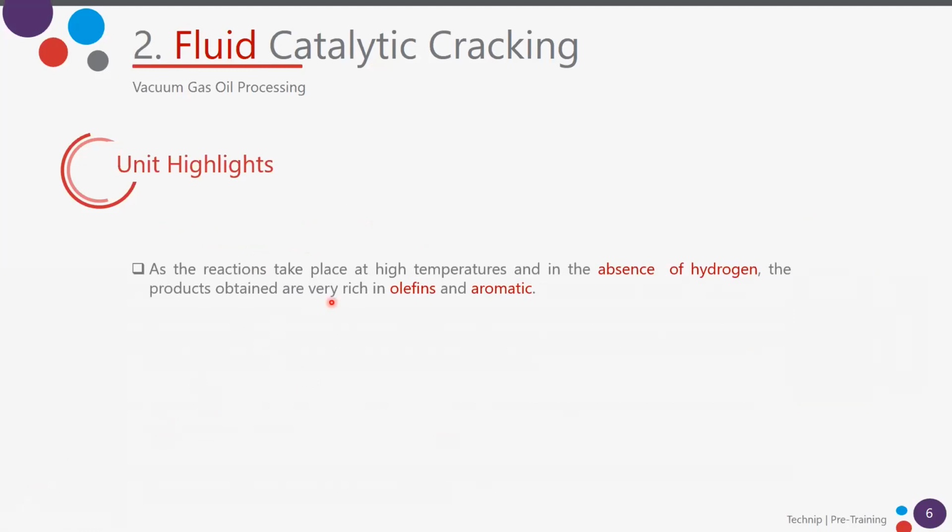As the reaction takes place at high temperatures and in this unit, we don't have hydrogen, so the products obtained are very rich in olefins and aromatics, okay? In this case, we don't put hydrogen for the reactions.